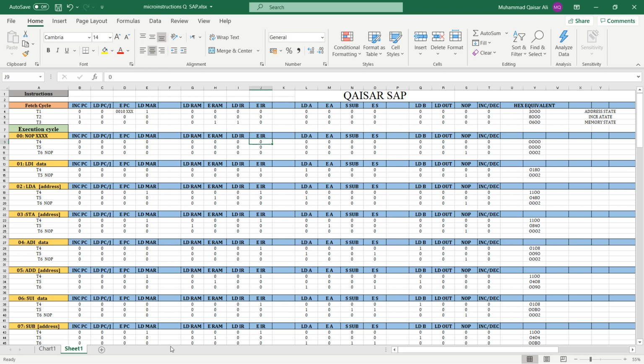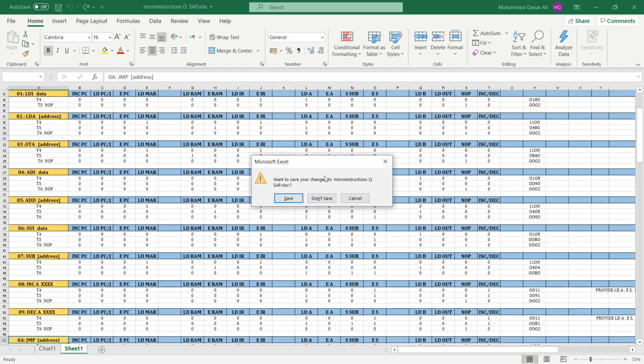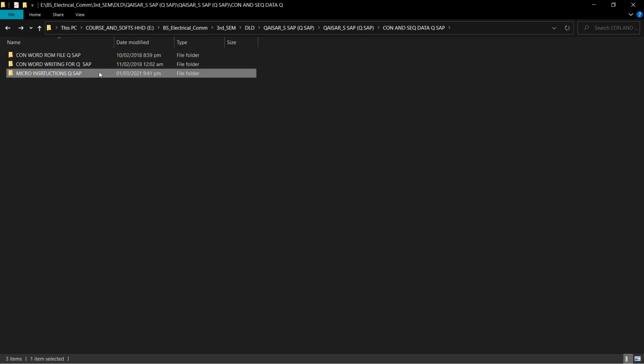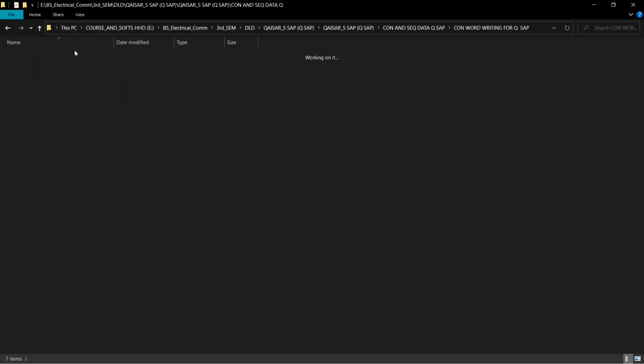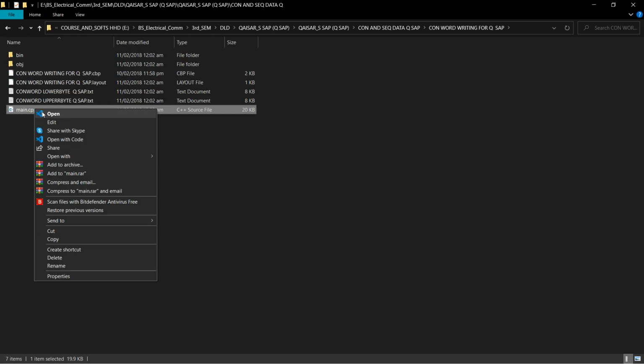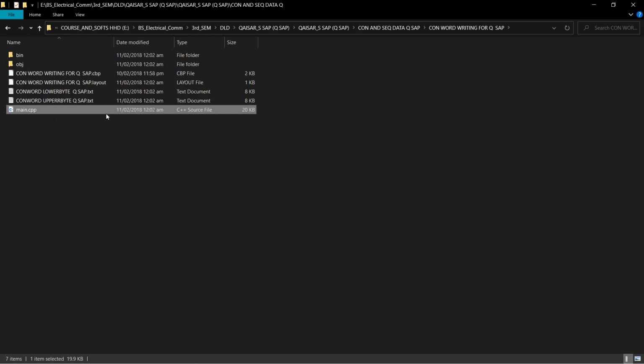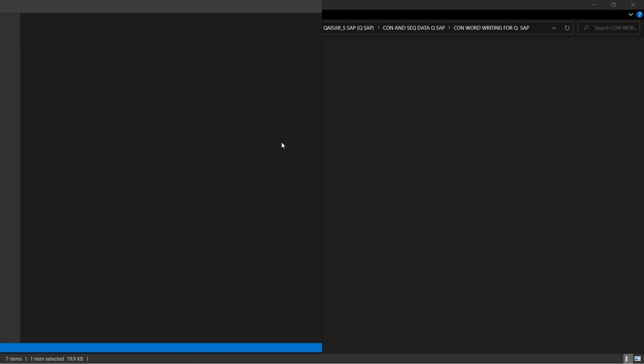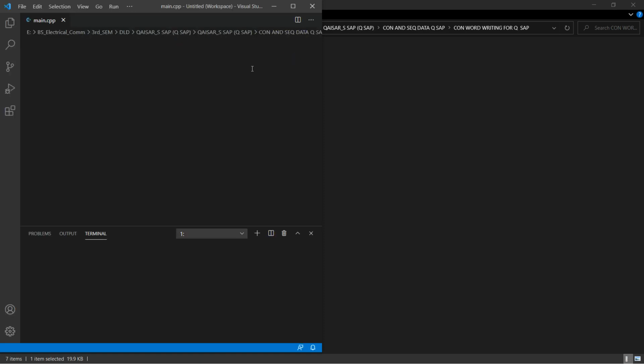So how do we achieve this type of input-output mapping? I did this job with the help of a C++ program. I wrote that program, which generated the desired output of the controller and sequencer for a specific instruction and for a specific time state in that instruction. Through that program I generated the file which I then uploaded to the ROM.